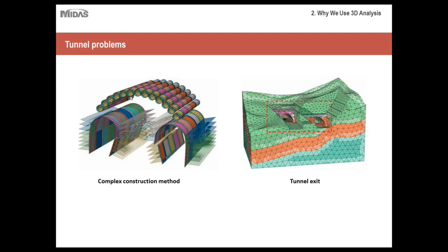And then also, as you can see here, this would be, I think, neighboring structures or ventilation, and just the geometry. Even though it's symmetric, it would best be modeled in 3D just because it's an adjacent structure. So you need to account for loading and displacements in the longitudinal direction as well. In this sort of case, typically strains in the longitudinal direction aren't negligible, so you need to model that in 3D.